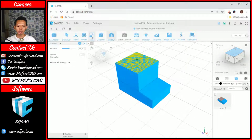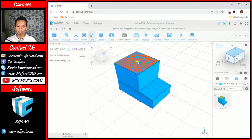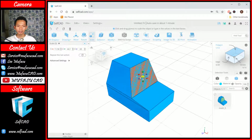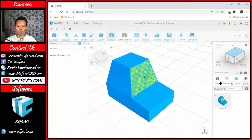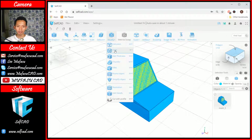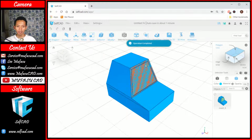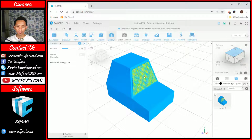And now you can use the scale command. You can click confirm change. You can scale from the center point, make it smaller to this point. Okay. Now I will select this face, and then in here I will use the insert command to insert new polygons. Okay, I will set the amount in here to 2. Next we can use insert again, and I will set the amount to 1. Now we can use extrusion to extrude this face, move to this point.